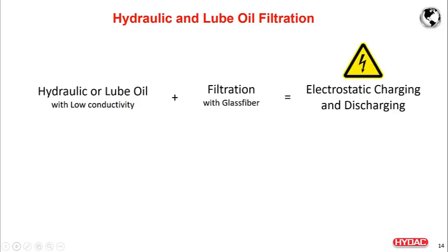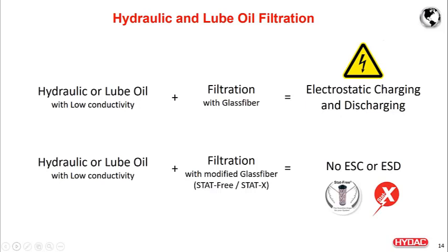Now, when you have hydraulic and lube oil with low conductivity, and you're utilizing the modified glass fiber that doesn't act as a glass but still gives you the good properties of glass fiber filtration, you're eliminating the root cause of the ion exchange. Because of the compatibility between the low conductivity oil and the StatX and stat-free, that charge generation doesn't happen, hence no electrostatic charging and no electrostatic discharging.